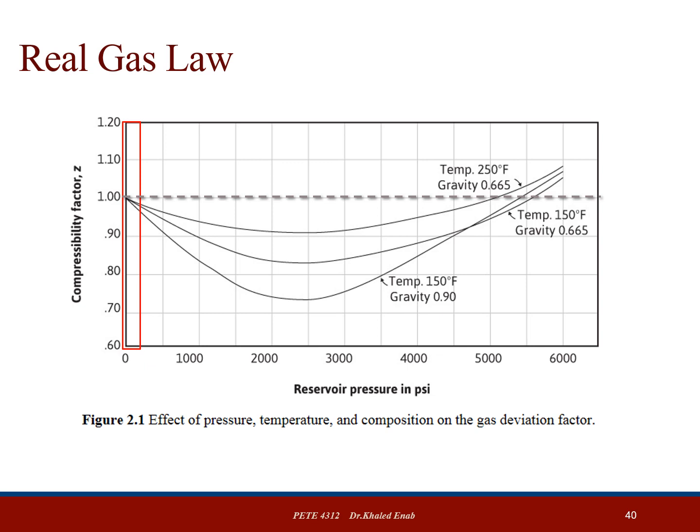And when we look at the same gas gravity, 0.65 and 0.65, at different temperatures, we notice that at higher temperature, gases do not compress as much. That proves what we mentioned earlier, that real gases will always behave ideally under low pressure and high temperature.